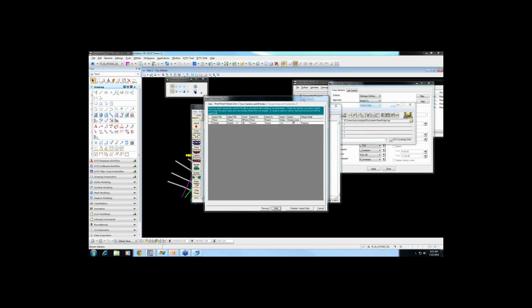Go to geometric data, file, import geometry data, GIS format. Navigate to wherever you put it. Hit OK. So this is the import screen, US customary. If you hit next, it'll flip to the next tab. This is telling you that this is a new stream in Reach, and it's in replace mode. So if you were re-importing it, it would replace the old one with this.